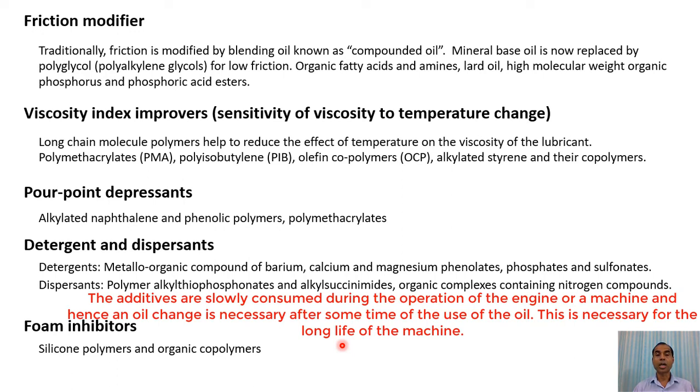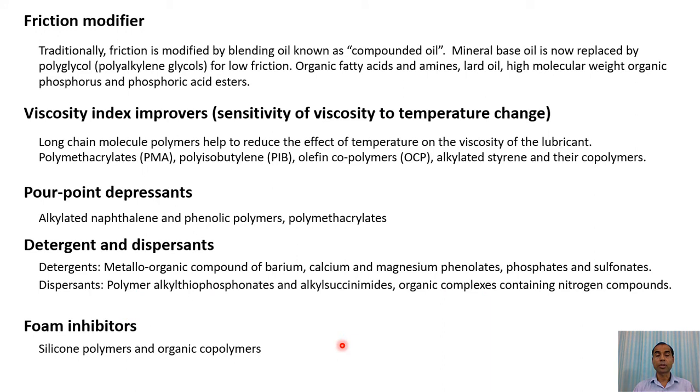And that's the reason why cars or any kind of vehicles have to have oil change at regular interval, because the oil quality continues to go down. It is not just the viscosity, but all the additives are consumed during the process. So this is the main aspect of additives for lubricating oils.